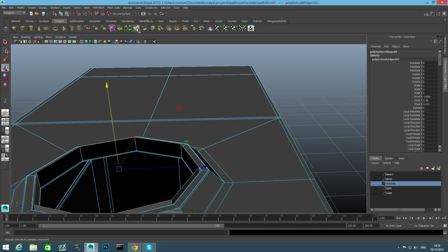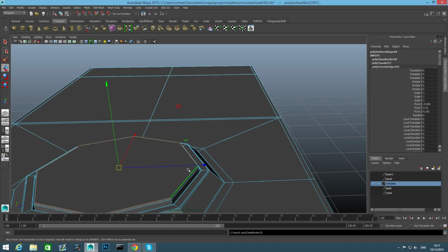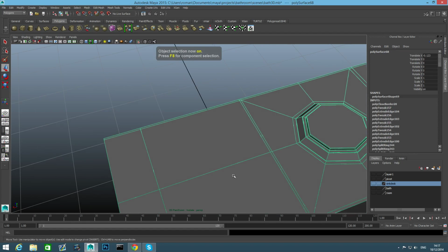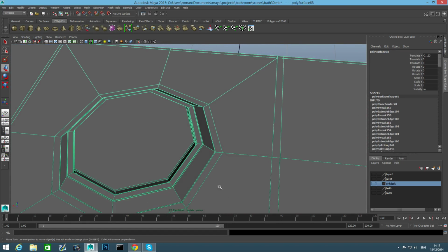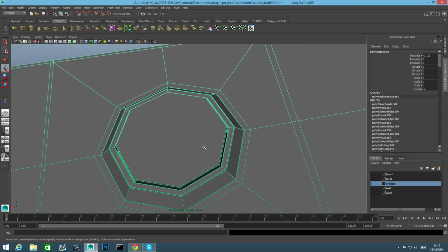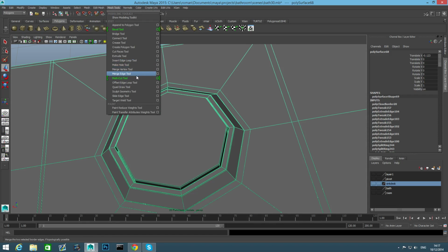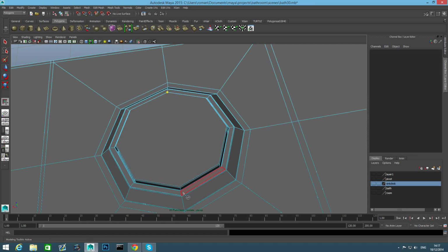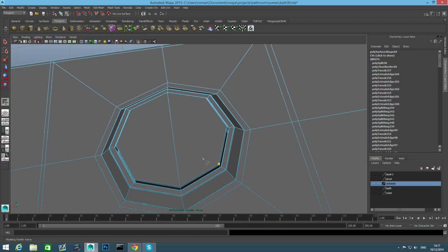and then you can extrude it once, just a little bit that way, switch to scale tool, and mesh fill hole, press F8, back to object mode, let's examine this. You can go over multi-cut tool, mesh tools, multi-cut tool, and snap and attach these two. Attach this one, that one here. Do the same over here.